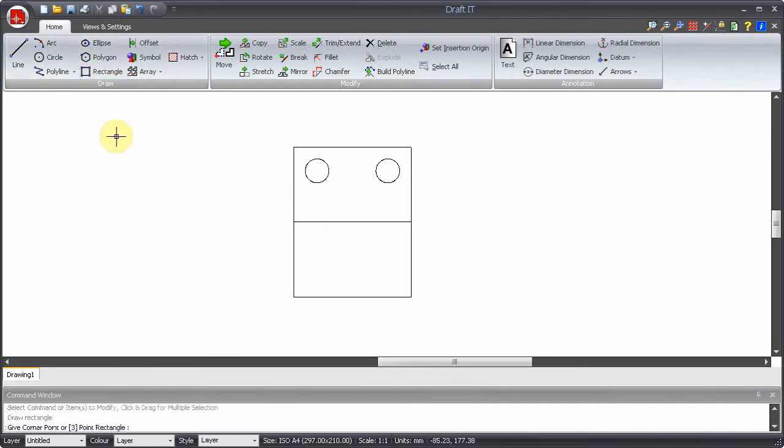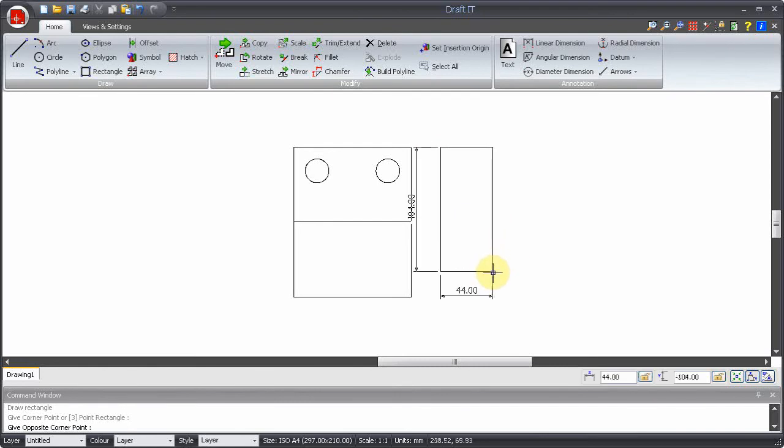We will demonstrate this by creating the side view of our component. We need to draw a rectangle which is 25 mm to the right of the existing view. Simply position the cursor over the point to go relative to and press R. Now you can define the relative distance using the dynamic dimensions or by typing values into the input boxes. Click to accept the new position. Now press F8 to switch on XY input mode and simply drag the rectangle to the required size and then again click to accept.